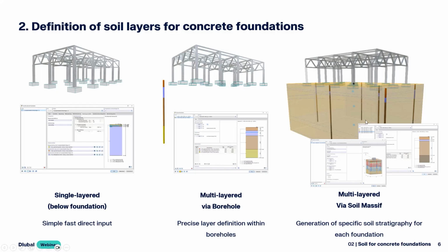There you can define the boreholes wherever you have them from your report, and you can generate the soil massif, and then automatically every concrete foundation gets the soil stratigraphy that acts below that foundation.